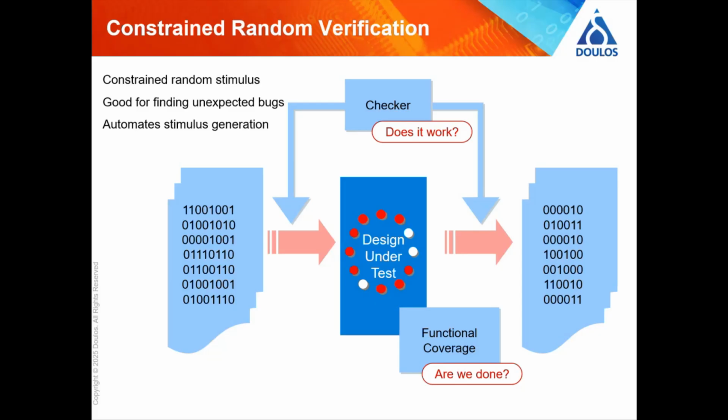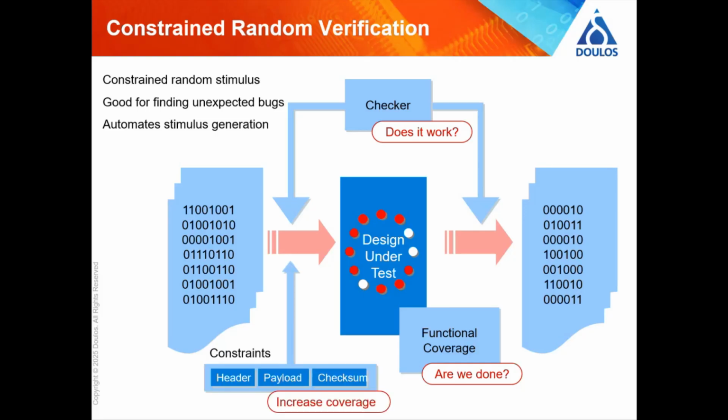And if the answer to the question is no, then what do we do next? Well, we have to somehow go back and say, I want to modify the stimulus that I'm pushing into my design so that I've got better coverage. So I've got a better awareness, first of all, of how much of the design I've tested, but also so that it's actually hitting the targets more. So the case of I want tests that cover the extra 30% that I didn't get the first time, for example.